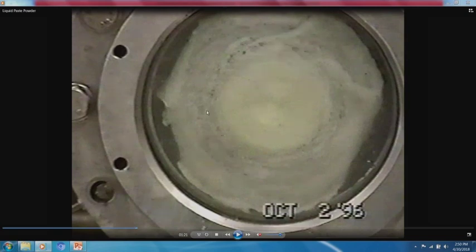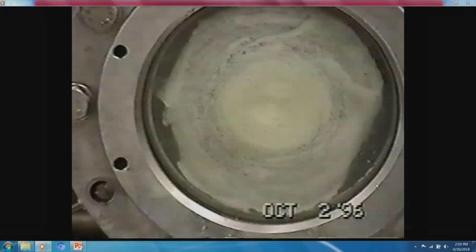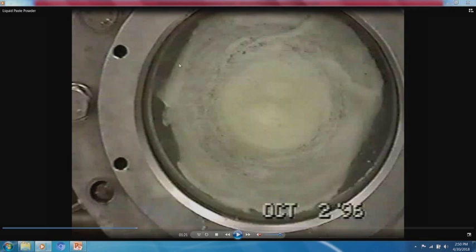Now here is an interesting flow regime in the fact that gravity is no longer working. It's pretty funny that you think of gravity and you don't realize that perhaps in your processing equipment it no longer is working. Nobody's ever told you that. Gravity doesn't work. Anyway, here is an example of gravity not working. That material is clinging to the wall. It is not falling off the wall. It is viscously adhering to the wall. So we have the one regime where it's down in here. We have this regime which is sticking to the wall and gravity's not working.